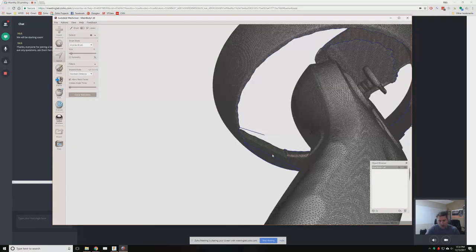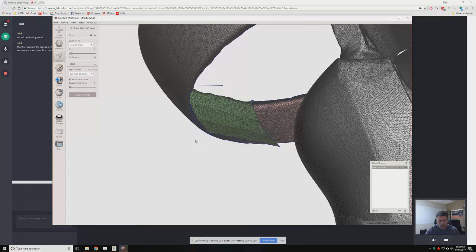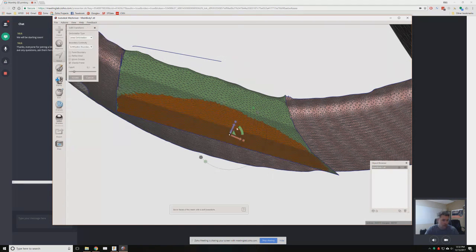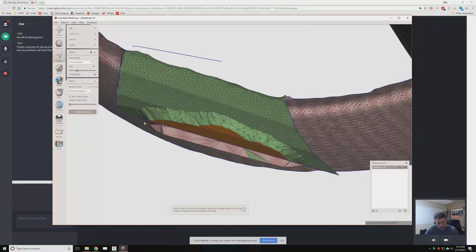There would be other ways, if anybody on replay asks this, to bend this. Actually, I do get questions on this. You can go to Select an area. Actually, I don't want back faces. Let me do this properly. Then go to Deform and maybe Soft Transform with a little bit of falloff. And you can refine the mesh like that. And that's actually okay, right? So I'm getting this more in the center. Again, that edge is causing me a little bit of issues.